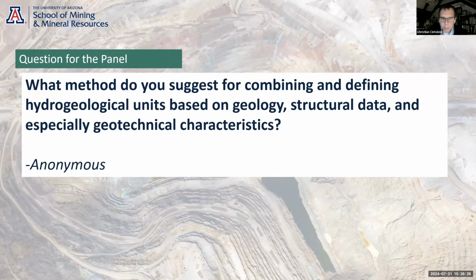To complement, I assume that the person who is asking is referring to a lot of borehole data. So I would recommend always using composite logs at the same scale, but what is missing here is hydraulic testing that is useful for defining the hydrogeological units, and geophysics. If you're referring to borehole data, then that's a way that you can assess the hydrogeological behavior of the different units.